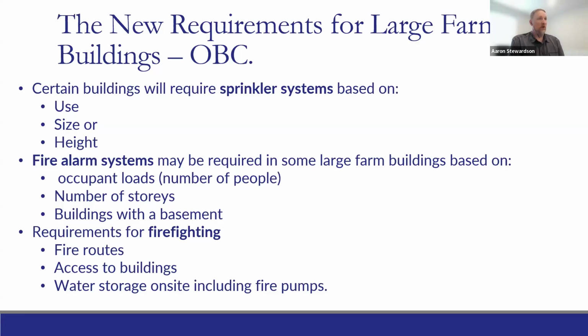Fire alarm systems may be required in some large farm buildings based on the occupant load, so the number of people in it. Not too much to be worried about here because the occupant load is quite substantial before the fire alarm is needed, right? And it gets down to the number of stories and if you have a basement in a farm building. Very, very few farm buildings out there have a basement within them that's going to trigger the need for a fire alarm system.